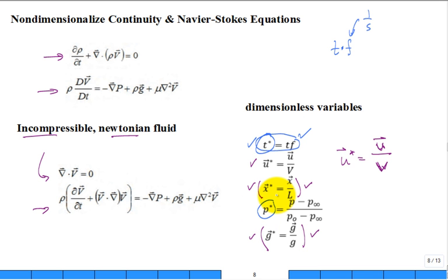And another one, a little harder, is maybe not harder, but it's a little more complicated. It's dimensionless pressure, but we're not necessarily interested in the magnitude of the pressure. It's the pressure difference, because it's the pressure difference on the front side and the back side that make a net form drag on my object. So we're going to take the difference between some far away pressure, some ambient pressure, free stream pressure, but that would just be a difference in pressure.